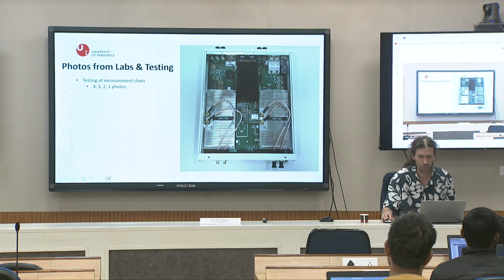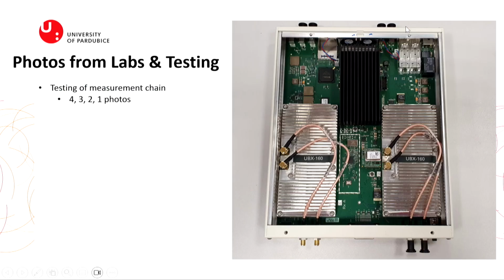This is the main board. There you have 1 gigabit, 10 gigabit, RF in, RF out, and so on. Under this is the FPGA, so you can even process in the FPGA if you don't process signals offline in MATLAB. You can directly program the FPGA and work there.